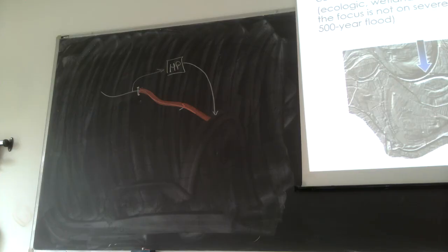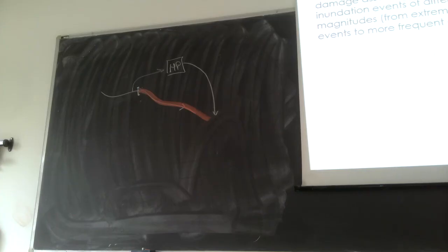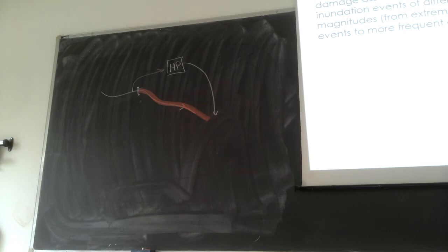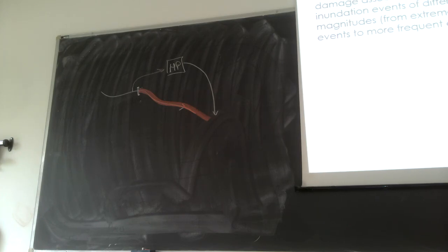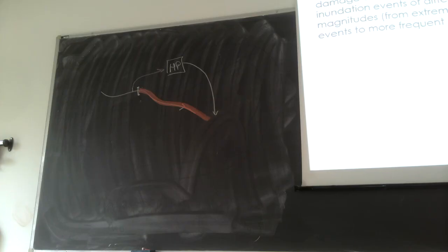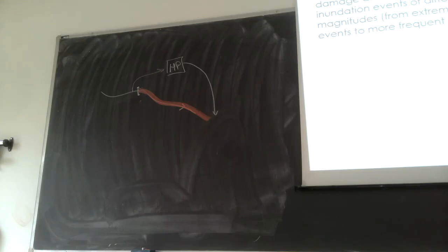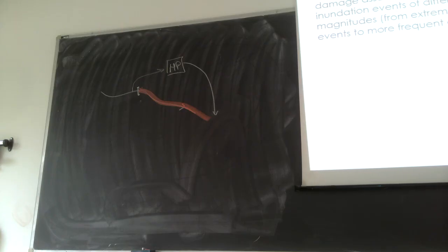Stream flow, river stage. Panel A is the rating curve. Now you have two additional panels, B and D. This is river stage damage. In the literature, this relationship is called a damage model. You may find an example of a damage model for agricultural problems or for urban environments.